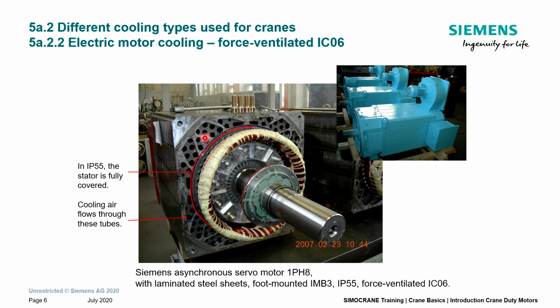Here the cooling air is blown through the ducts of the stator, and in that case this motor has a degree of protection of IP55. I will explain soon what does this IP class mean. And here you see the housing of the motor, you see the external fan, and in that case the air is not blown via the surface, it's in the stator sheets package.